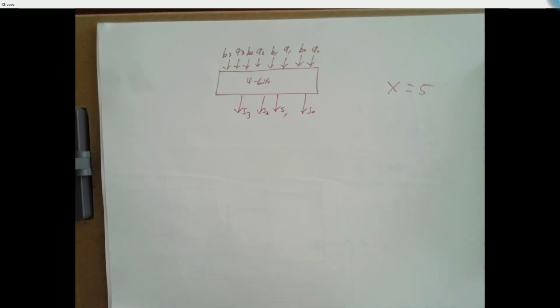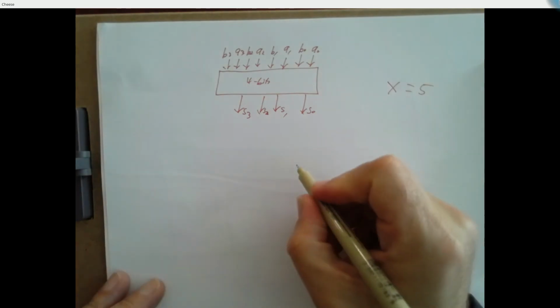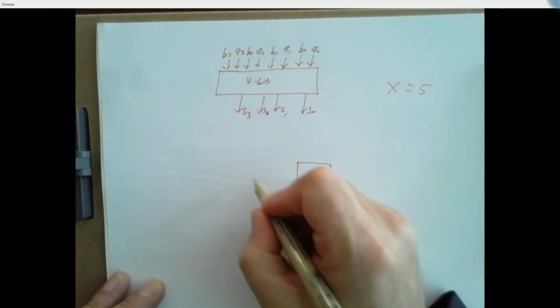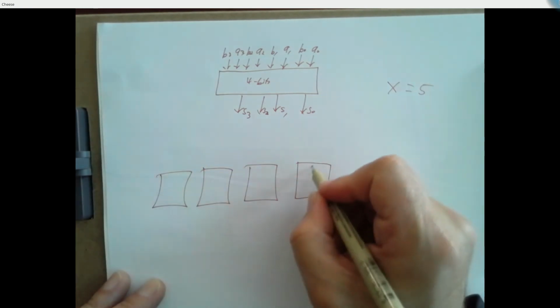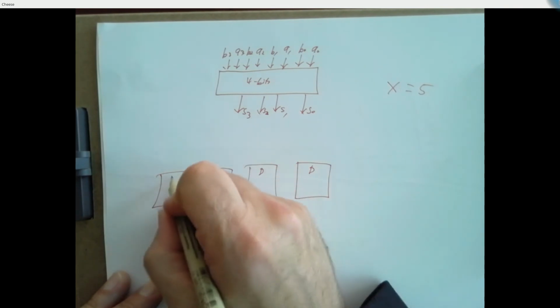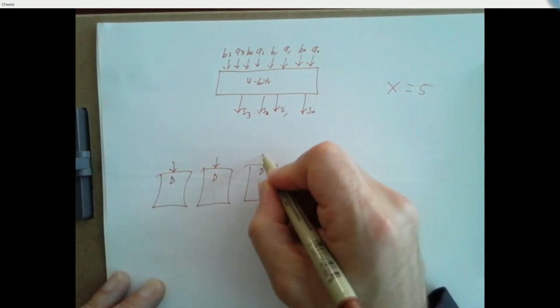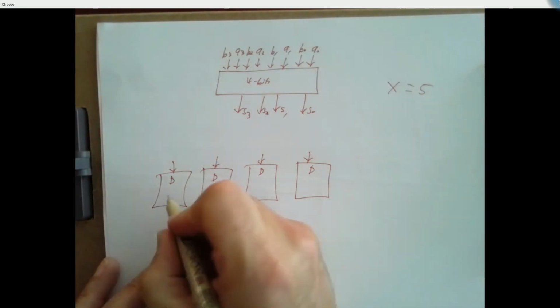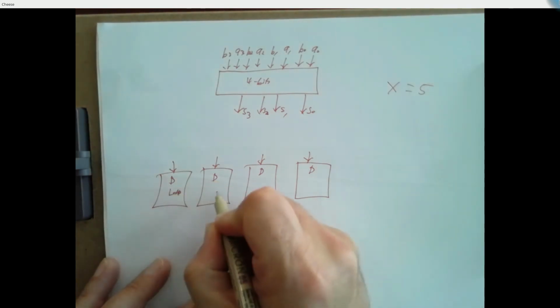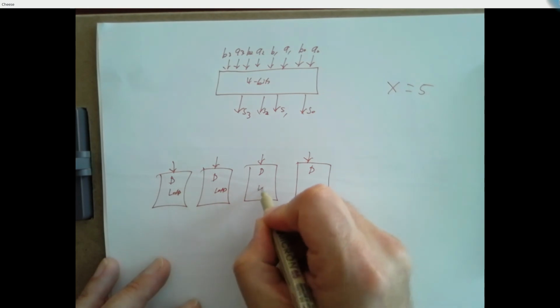5. So this box that can hold a number, your number is a bunch of bits. This would typically be something like a bunch of D latches. So we could build a circuit like this. And I'm going to change the orientation of these things. So I'm going to put the D inputs on the top, and I'm going to put the load inputs on the right.